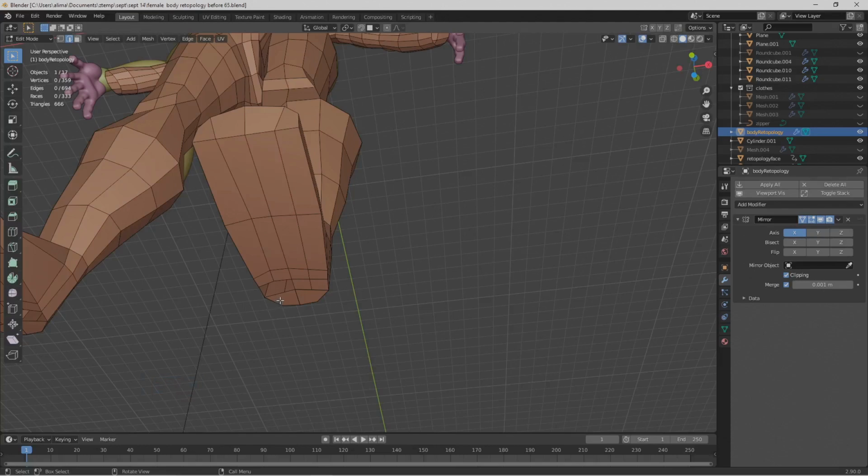Okay, I'm going to hover here. Hold control. Press R. Left click once, left click to lock that in. I'll select here, hold shift. Press F to fill. Select here, hold shift. Press F to fill. So long story short, whenever I'm selecting more than one edge, I'm holding shift typically.